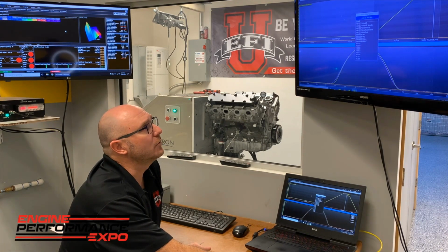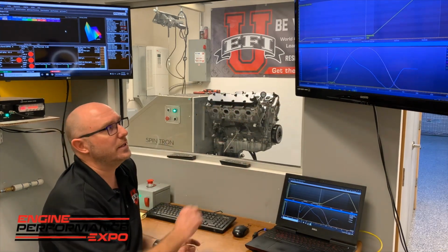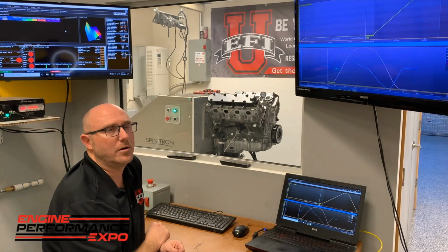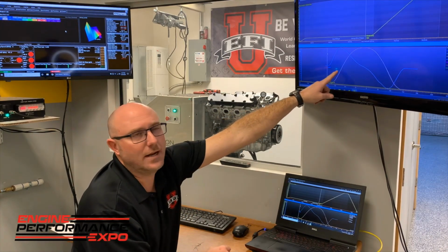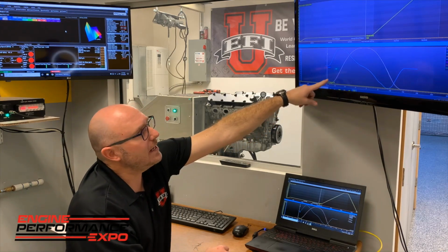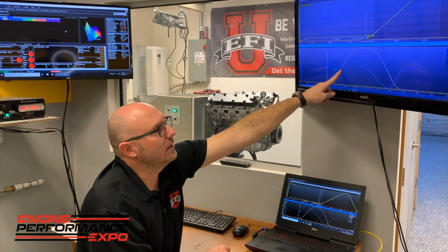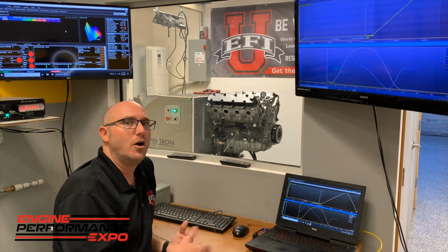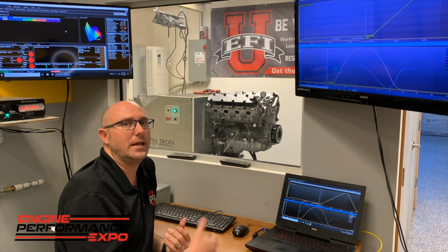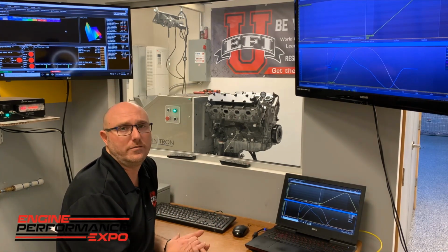And if you're not real good with your calculus, the velocity curve you're seeing here in blue is simply, for any given point in time anywhere on the lobe, what we have in the lobe is the lift at every point. But if we take the lift at this point and measure the difference between that lift and the lift at the point right before it, what we would get is the change in lift over the distance we covered. So it'd be like feet per second, miles per hour. That's a derivative that we call velocity.